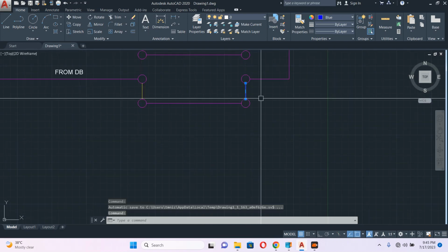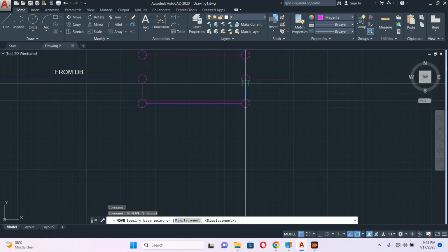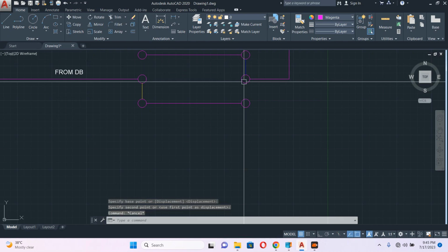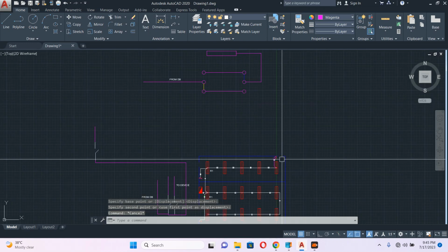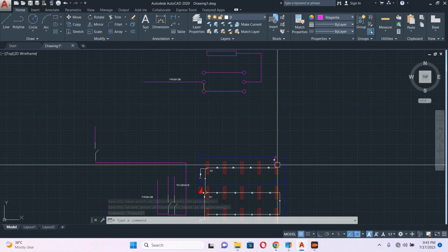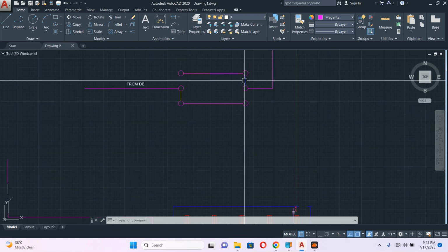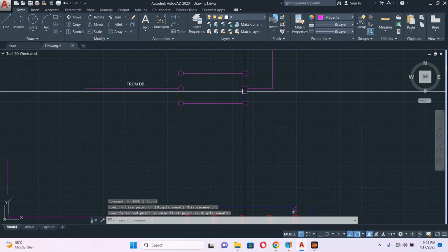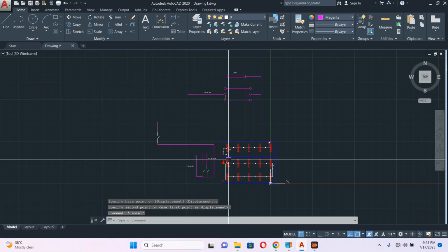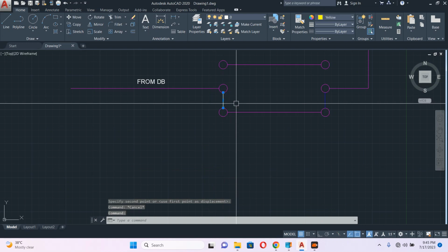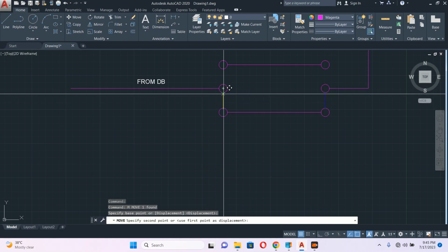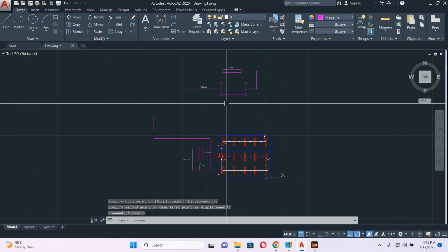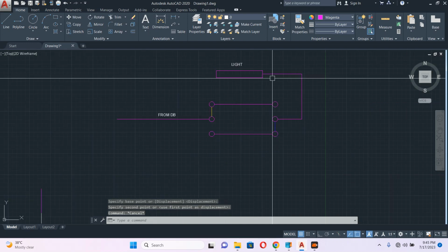I travel up to here and I am switching this switch. So what will happen? This will travel from here to here. Then the light will go off. Again I am coming here, switching on from here to here. The light will work again. From here I am switching off again. So this one will go to here. This is the two-way switch theory.